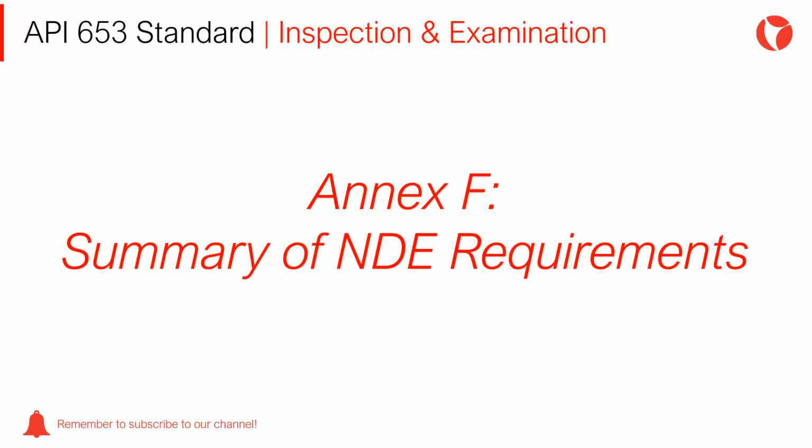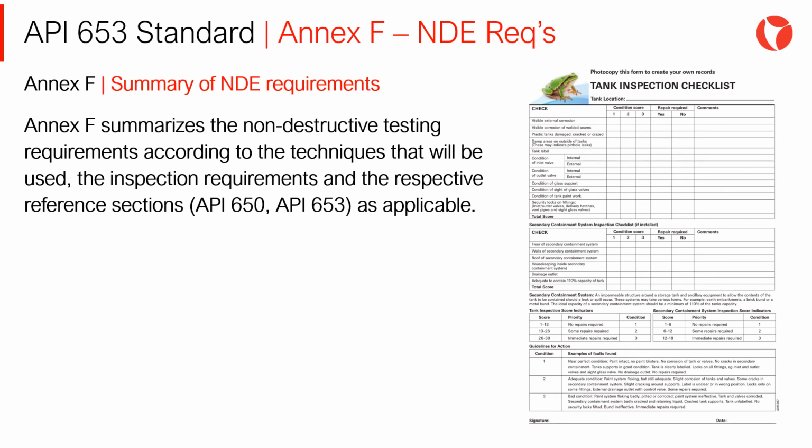Annex F, Summary of NDE Requirements. Annex F summarizes the non-destructive testing requirements according to the techniques that will be used, the inspection requirements, and the respective reference sections of the API 650, API 653 as applicable.